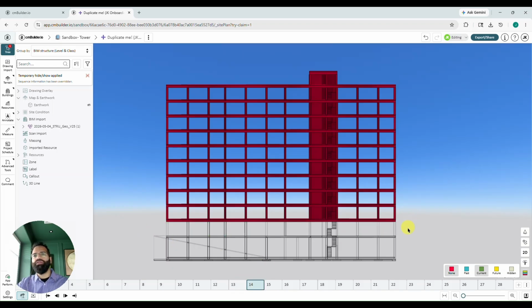All right, let's head up the rest of the building and do the same thing using my selection and deselection traps, as well as Control B to attach these elements to my schedule. Milestone 16 here calls for my level 3 slab, so I'll use my selection trap to select that and the deselection trap to deselect my columns before tapping Control B on my keyboard to attach them to milestone 16. Milestone 17 is my tower crane mobilization. We'll skip that and head to milestone 18 where we'll grab our level 3 columns. Once again, tapping Control B on the keyboard.